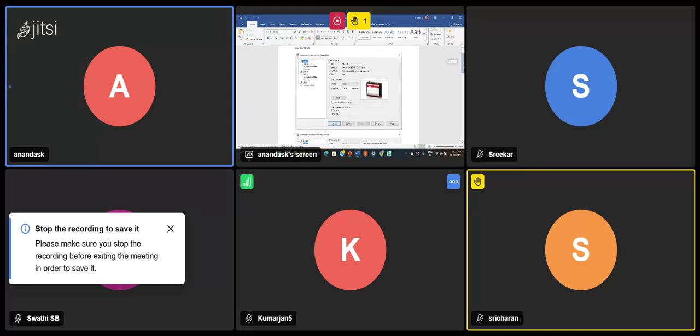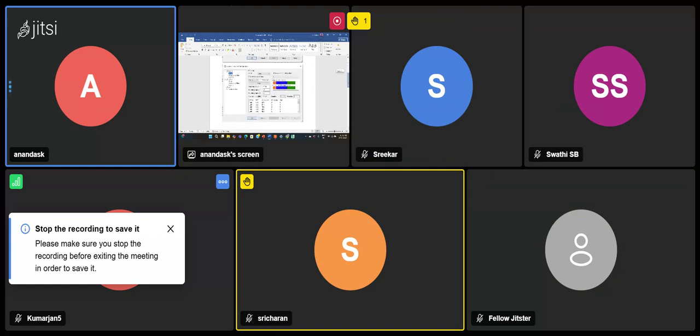If you have the hardware, it will show the type of hardware. Here the controller is the Vector CAN or CAN FD, and the CANpiggy high speed. Here you can see CAN and 500k baud rate. For CAN FD, you have to set it like this: ISO CAN FD baud rate, 500k, and data rate is 2000.